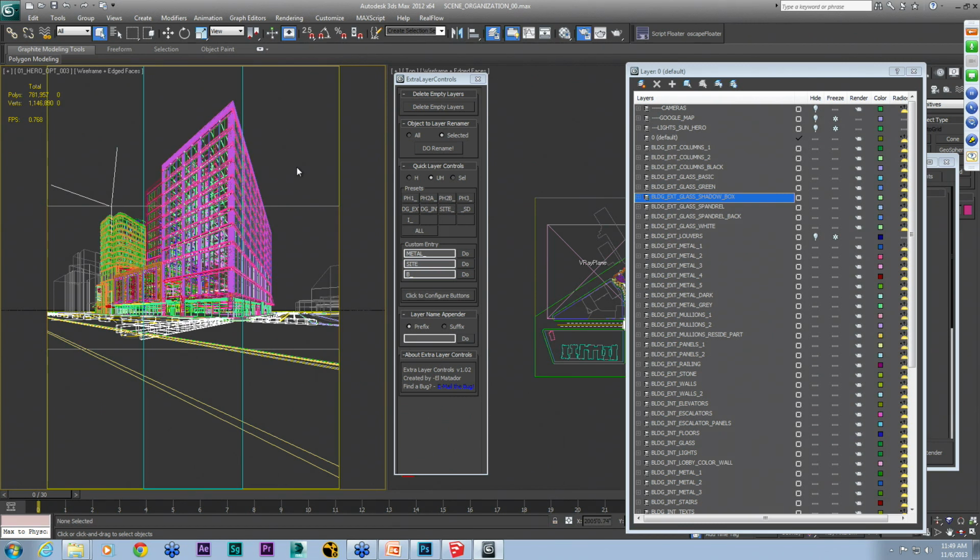One of the things that we do a lot is, if you look in the office at the images on the wall, I can guarantee that none of those are a direct render out of Max. A lot of those have different render elements layered over, which people will talk about in compositing, but we render a lot of mats too, so we can selectively control colors on different objects. By layering things by material, you are able to select those objects and make mats very quickly.